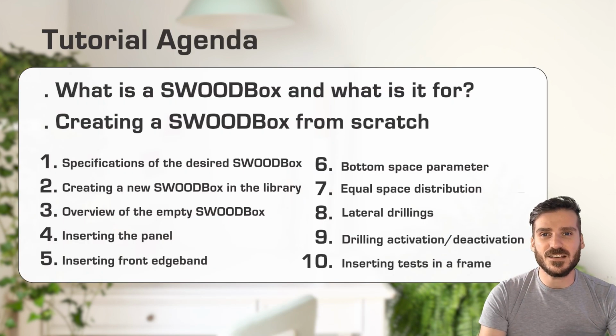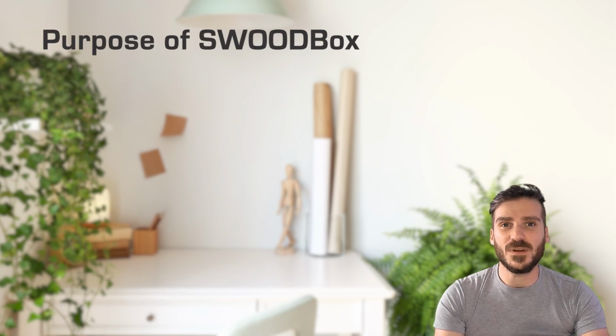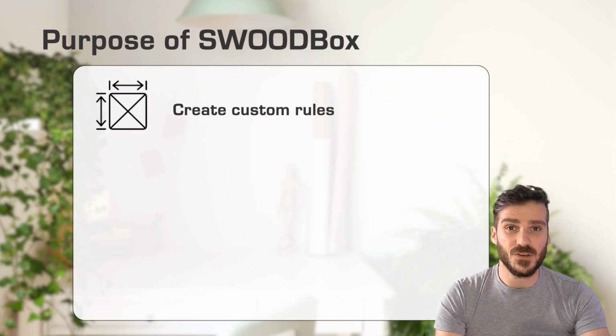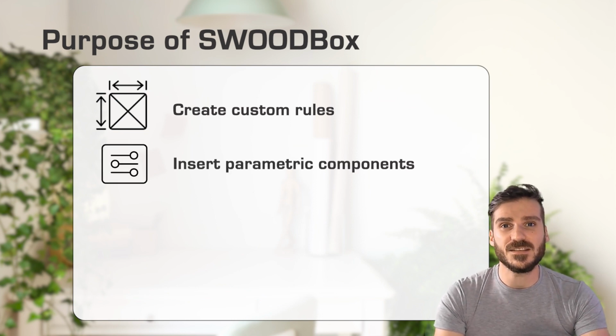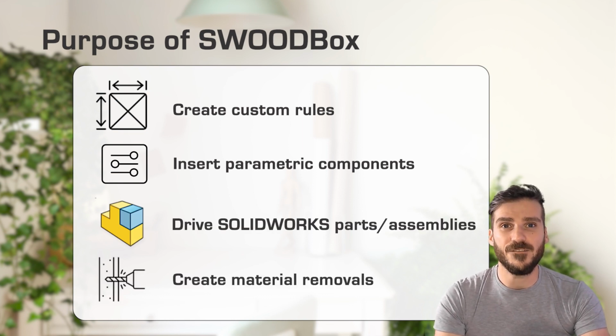As you can see in the agenda, we will first define what is a SWOODBox and its interest. And then we will see all the steps to create a SWOODBox from scratch. First, the interest of a SWOODBox is to be able to create custom rules, insert parametric components, drive SOLIDWORKS parts and assemblies, and finally create material removals in the insertion volume of the SWOODBox.